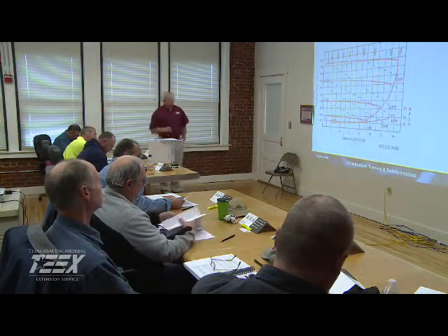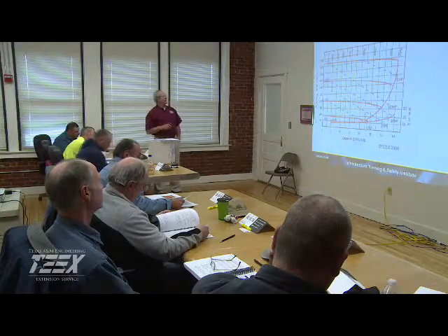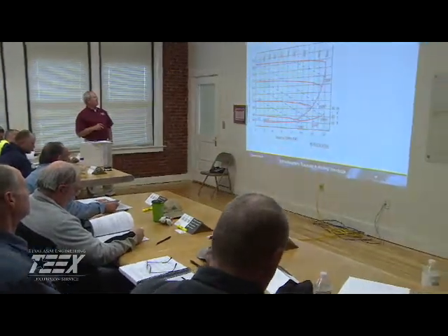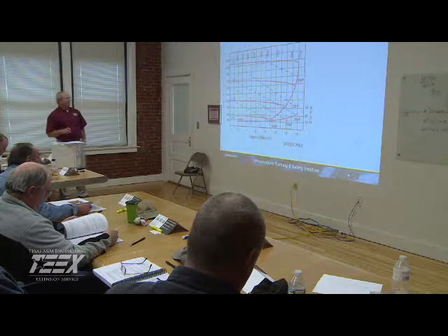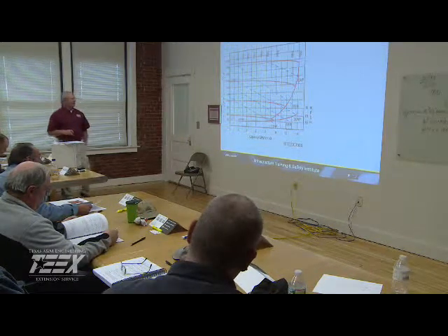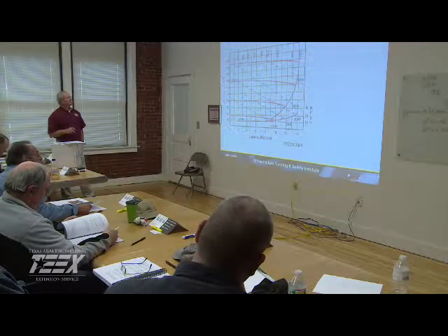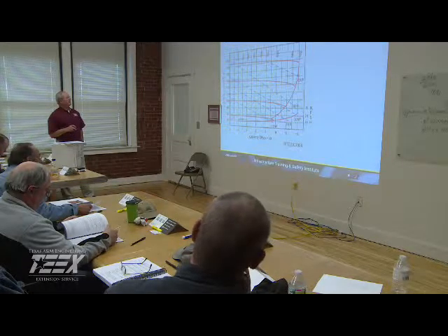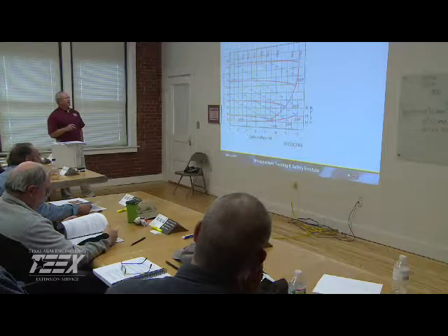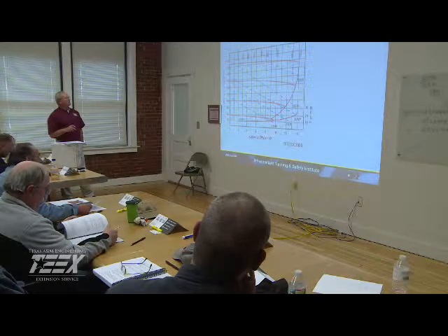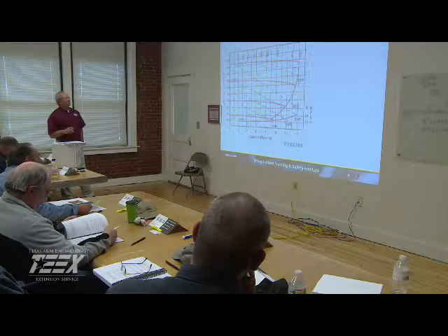Pump curves. Basically, let's say that I had a pump and it was 180 foot of total head, and let's say that I needed 800 GPM. I'd come up here where this intersected right here. You'll notice that I'm 55% efficient. That's my pump efficiency. You'll notice that my motor horsepower curve right here is at 75, so I'd have to be at least 75 horsepower.